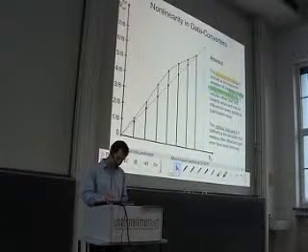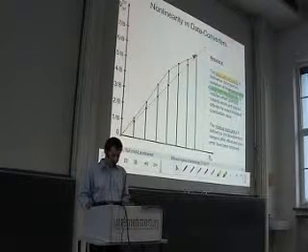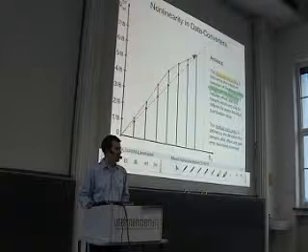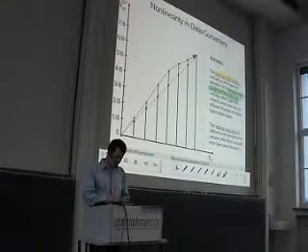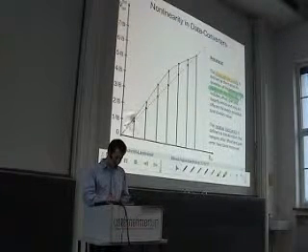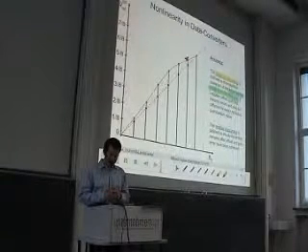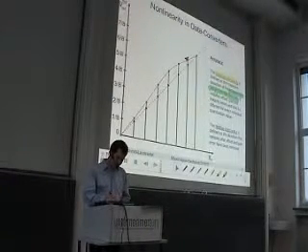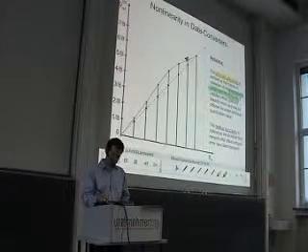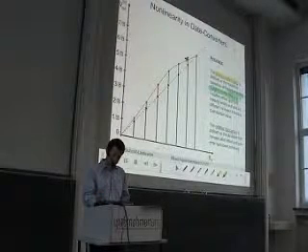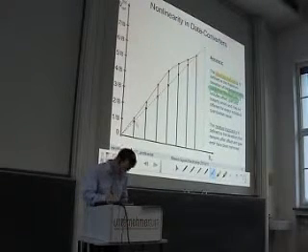Let's look at these characteristics. The black dots indicate the ideal DAC characteristics for a 3-bit DAC. Then we get a DAC, we measure it, and for instance the values we get is the red curve. So the absolute inaccuracy is the deviation of the red curve from the black one that indicates the ideal values. So the maximum deviation of the actual analog value from the ideal one. So we can define this for each point.